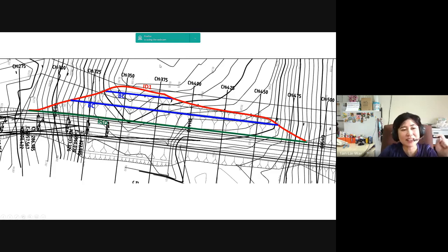That means it intercepts rainfall runoff from upstream, from going into the other drains. The rain on this area here won't go into the bench drain because you already have this interceptor drain that intercepts all the runoff from upstream here.